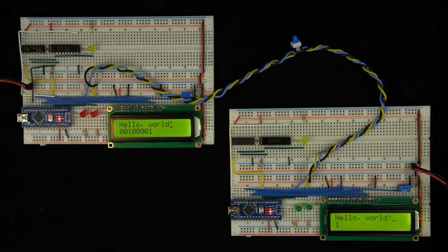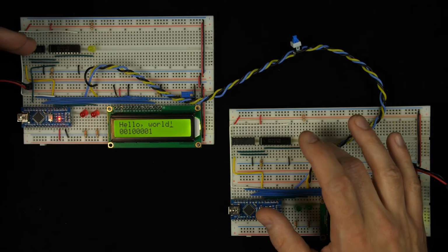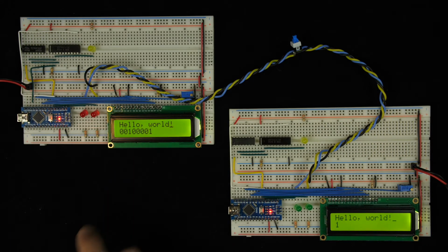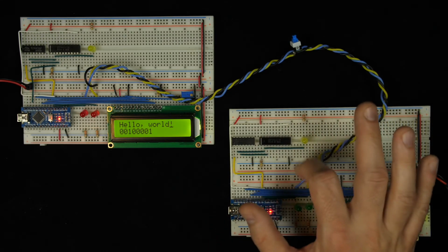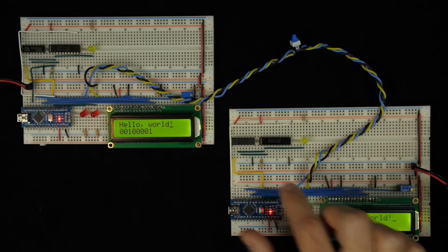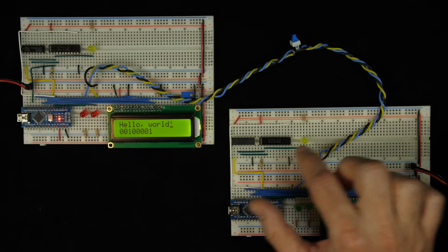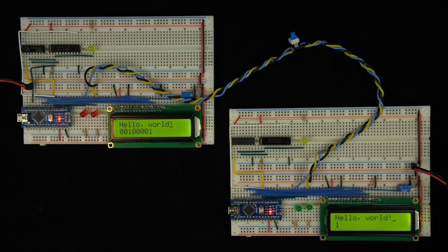So that suggests that we must have sent an even number of 1 bits and received an even number of 1 bits. And of course, our message hasn't changed. It still has an odd number of 1 bits. But now we've also sent the parity bit, which remember was a 1. And that's actually this one here that you can see on our receiver. But of course, our parity computing circuit is very simplistic. It doesn't know the difference between the data bits and this parity bit. And so it just wound up counting another bit, and we wound up with an even number of 1s.